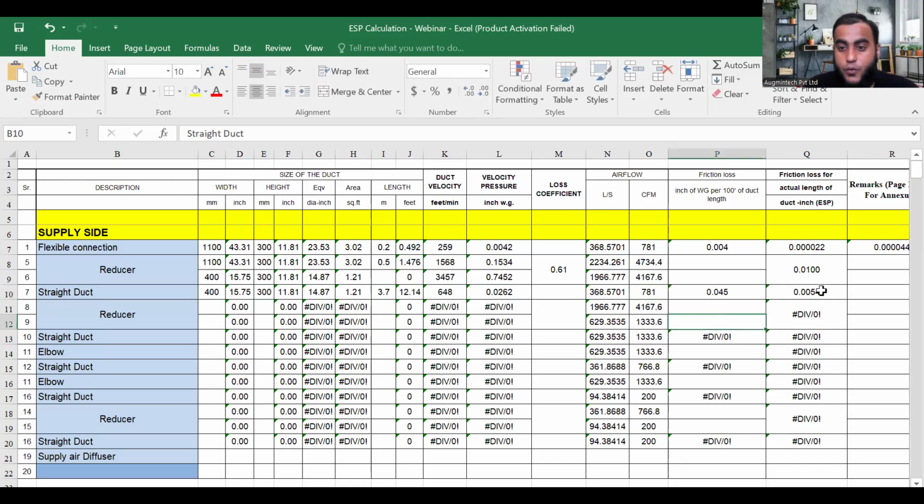And remember, why was it showing so high previously when we were calculating the reducer friction loss? Because I had not changed the flow value. Just change the flow value here also. In manual calculation by using the formula, or directly as I have entered here, if you go for the formula, you will get the same value. So don't worry about that.